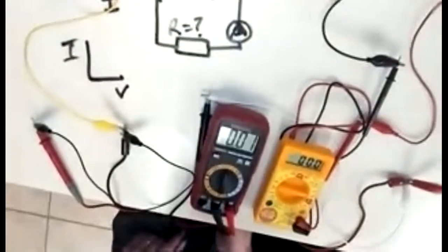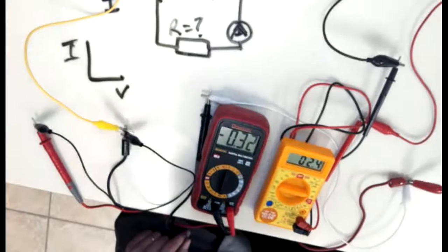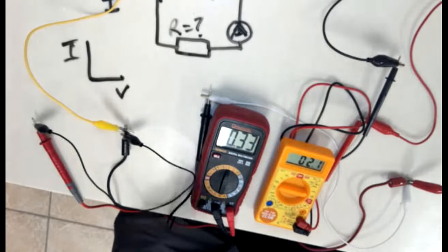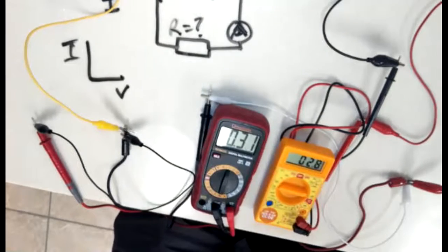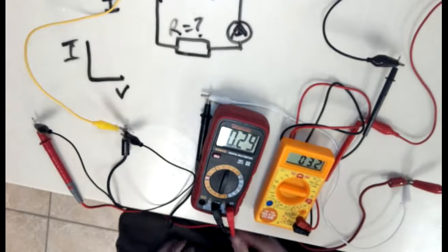So we have 0, 0. I'm going to increase the voltage. As the voltage goes up to 0.3, the current increases to 2.4 milliamps. So 0.33, 2.4. I saw those numbers together. And if you see a set of numbers up there that's slightly different, record them. That's empirical data, right? There's nothing wrong with it.